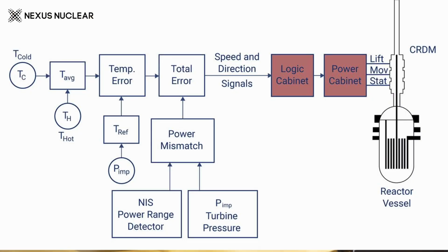Time is a major concern for these operations. For one step, all the actions should be within the limit of 0.7 second. In case of a scram, the shutdown, we normally say up to 2 seconds or a maximum of 3 seconds. Within 3 seconds, the whole RCCA should be inserted. That is in case of any abnormal accident or any other design basis accident cases also. The whole shutdown operation should be within 2 to 3 seconds.